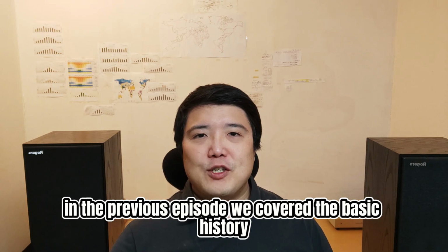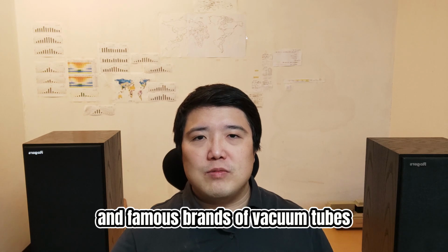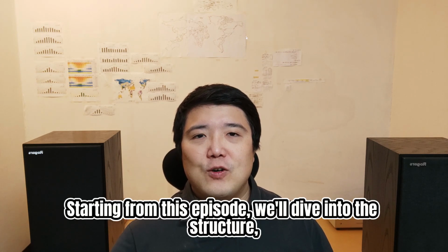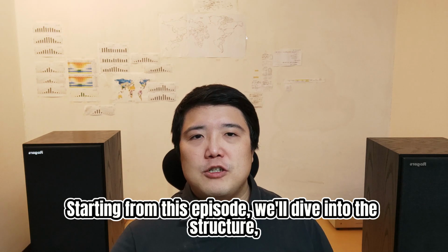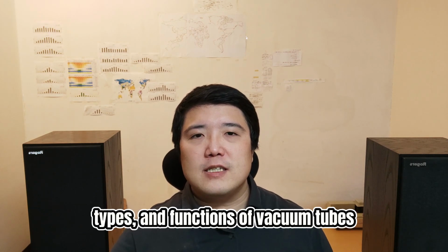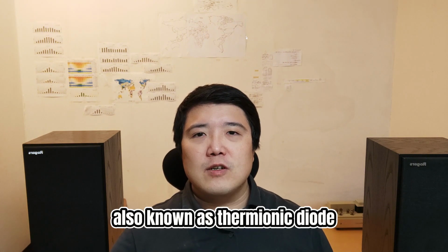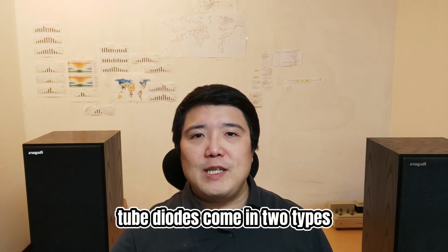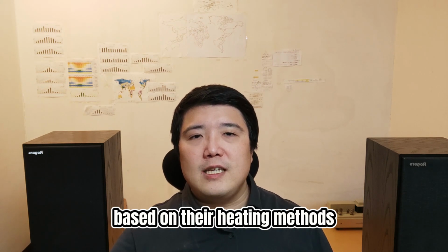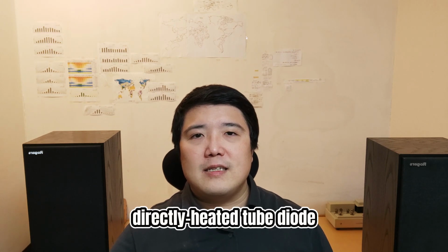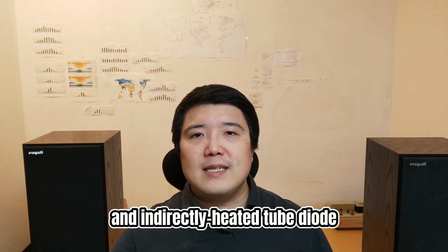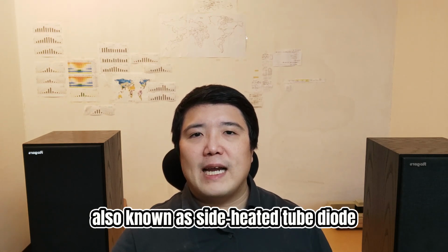In the previous episode, we covered the basic history and famous brands of vacuum tubes. Starting from this episode, we'll dive into the structure, types, and functions of vacuum tubes. Let's begin with vacuum tube diode, also known as thermionic diode. Tube diodes come in two types based on their heating methods: directly heated tube diode and indirectly heated tube diode, also known as side-heated tube diode.